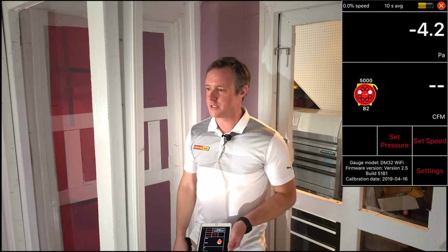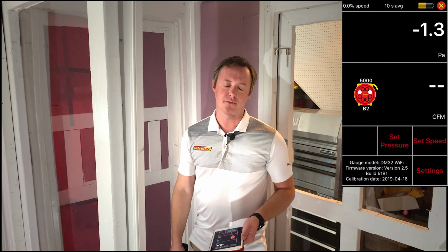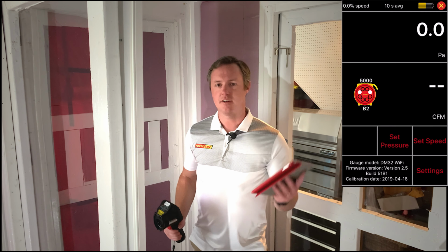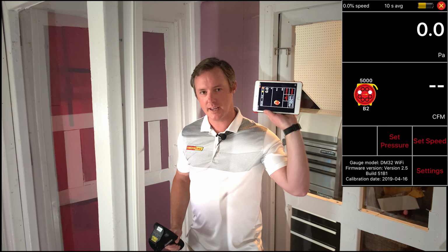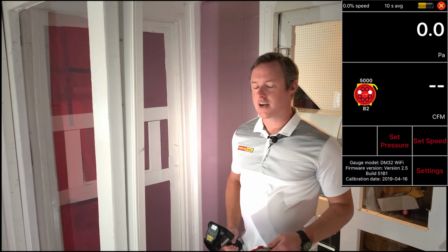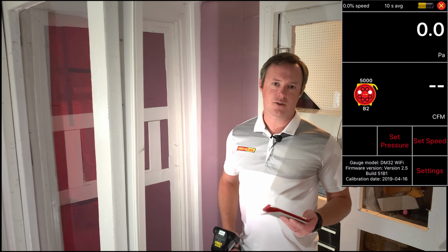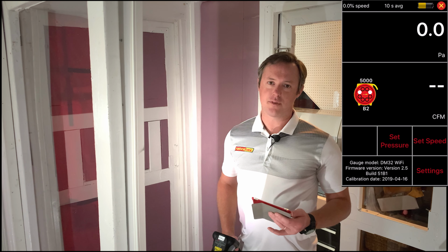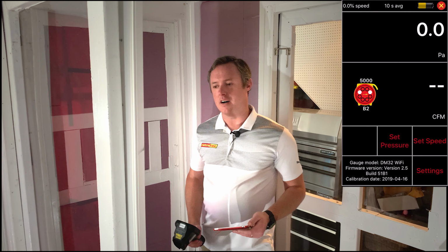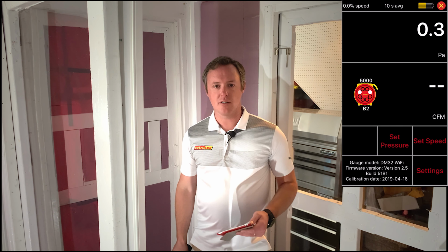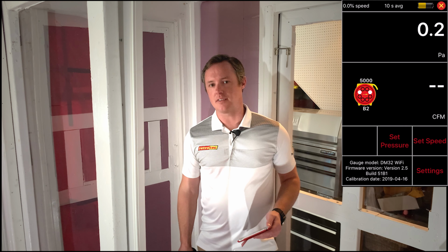You would use your blower door when you're inside the home, which is typically how you're gonna do it. That way you can depressurize, walk around the house, you can have your fan control in one hand and have the camera in the other, and then look at some of the common culprits that we see, usually at the corners of the house, around different penetrations that go through the ceilings and the floors, same for exterior walls. And then those connections there at interior walls of the ceilings.